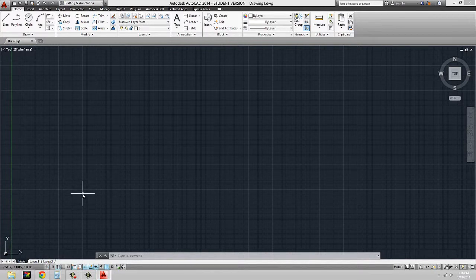To the right of the coordinates are drafting settings. We'll look into these. They have snap mode, grid display, ortho mode, polar tracking, and so on. We'll be covering some of them, but not all of them. So get used to working with them, accessing them, and see what they do, because a lot of this is really personal.